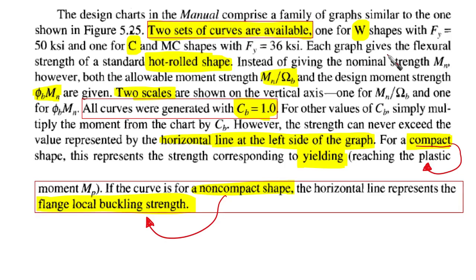Each graph gives the flexure strength of a standard hot rolled shape. So we are talking about hot rolled shapes. Okay, it's not built up sections. For built up sections you need to calculate it using your in-house calculation sheets or so. And instead of giving the nominal strength Mn, however, both the allowable moment strength and the design moment strength are